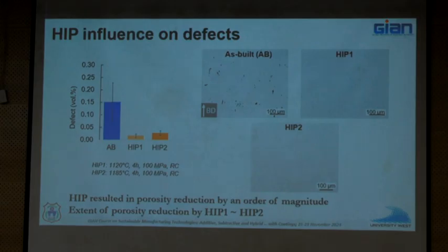So, all that action is going to happen later anyway, and that doesn't happen in as-built condition. When you do EBM or SLM of a superalloy, you don't get the phase constitution that you want. As I showed in the motivation, in fact, you get some Laves phases and things like that, which you must get rid of, right?